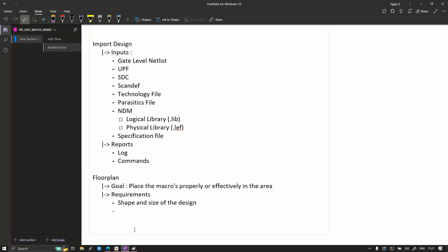So a separate file called the top design format, or .io file, the input output information file, will be having the location information of the ports. It can be provided in any format, either a Tcl file or a PDF file or a PPT file or a pictorial representation. Anything they can provide you, that particular information. Okay.